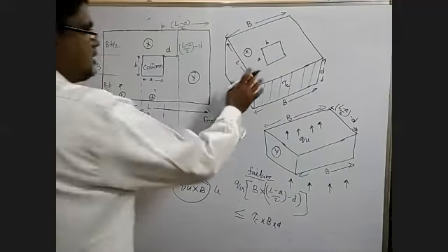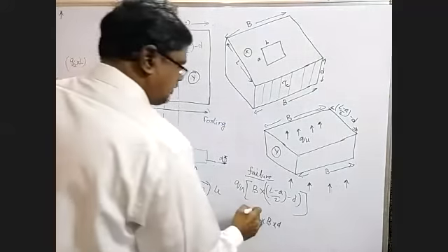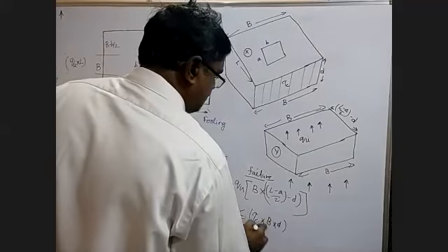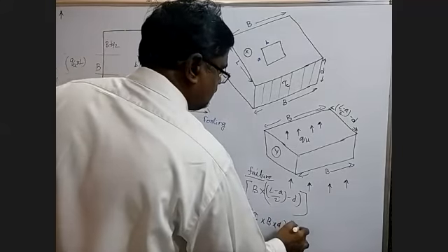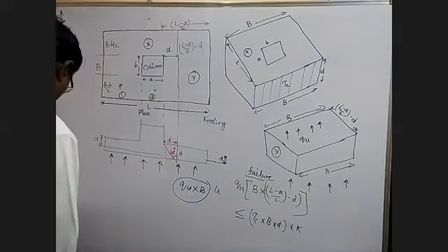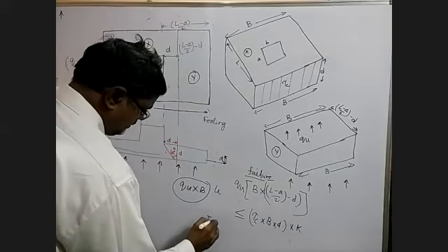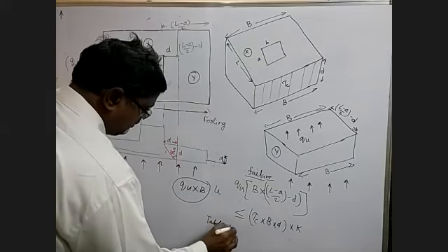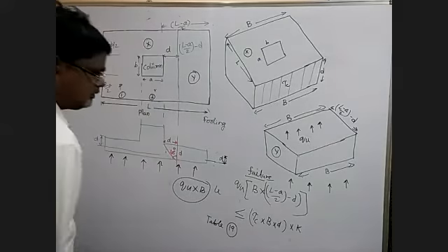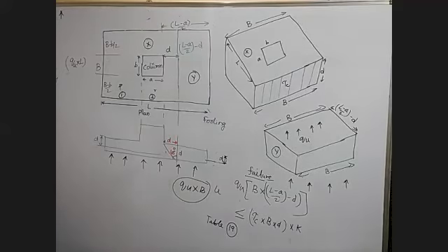So this is just like your solid slab. For a solid slab, this value should be multiplied with K. The K value is in Table 19. We already did it here, Table 19 has the K values. For a thickness greater than 300, the K value is 1.